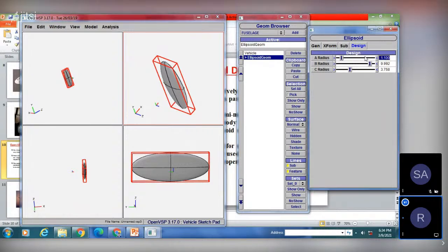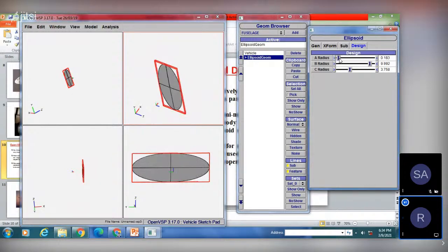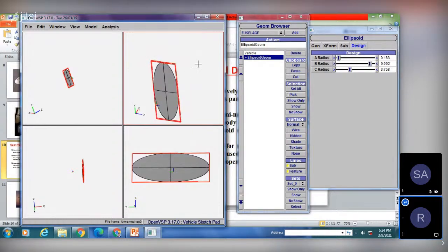Okay, so see here, if I maintain this 0 and I enter here, because of the overlap, the surface is not that clear. So that's why just keep a small radius for that overlap part, so that you can avoid such overlapping surfaces.